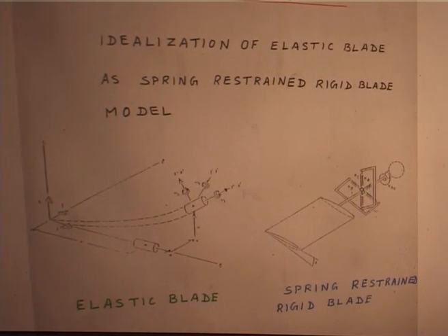Okay. But you look at the frequencies. So, in the rotor blade dynamics group in the helicopter company, a couple of guys have the job to run every day the natural frequency and mode shape in each mode. We have developed a code now that is given to HAL. We can analyze an actual blade. Of course, there are a lot of small details of a real blade which we have to take into account. Once you have the code ready, every day you will run it. You may not know how it is developed, but that is a finite element code.